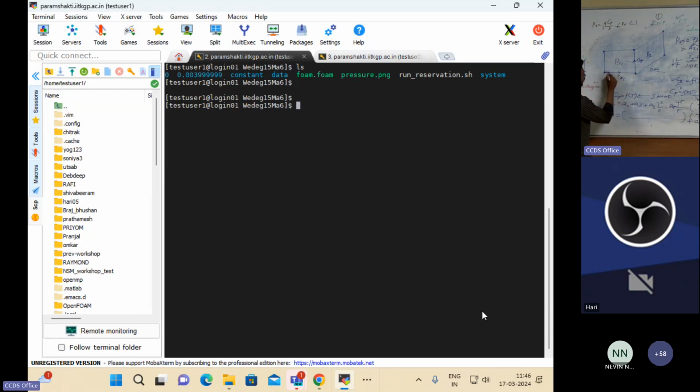If you want to make a very fine mesh over here, those entries I've already fed in, and gradually you will increase the spacing as you move away in y. Right? So you are capturing all the interaction process over here. If you want to use a uniform mesh, then unnecessarily you will discretize this domain as well, where nothing is happening.